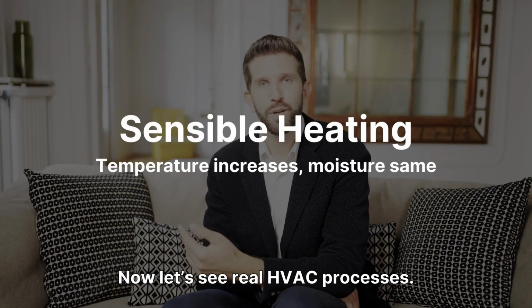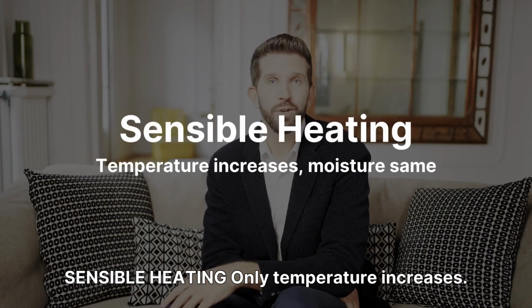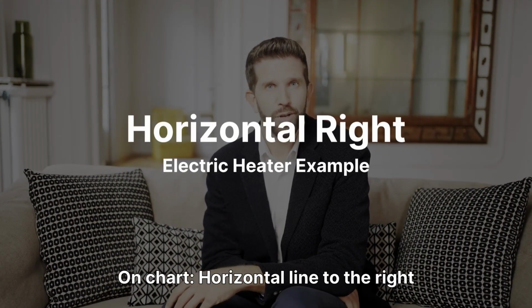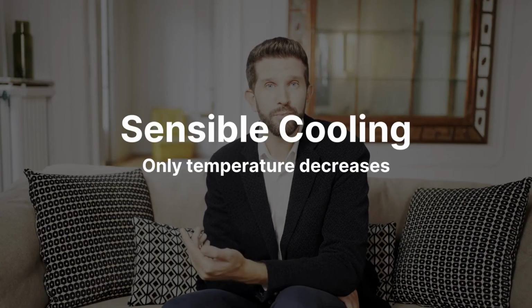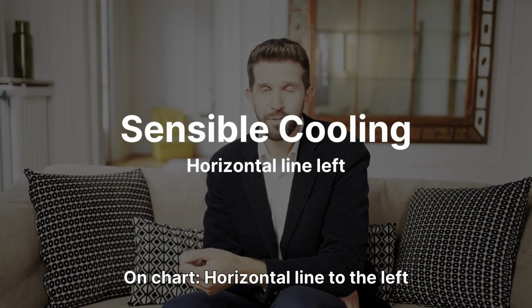Now let's see real HVAC processes. Sensible heating: only temperature increases. Moisture remains the same. On the chart, it is a horizontal line to the right. Example, electric heater. Sensible cooling: only temperature decreases. No moisture removal. On the chart, it is a horizontal line to the left.